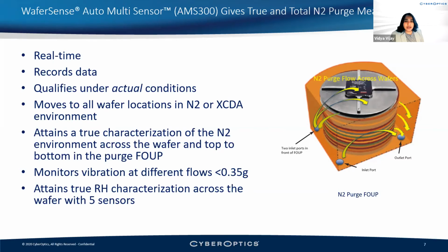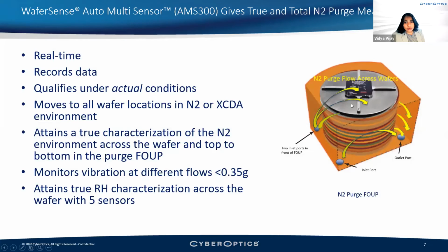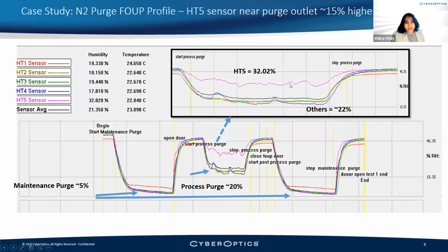So as it goes, it records data and communicates wirelessly via Bluetooth. So the customer can see what is happening when they do a process change or an improvement. For example, here, there are 5 humidity sensors as we saw. There is one in each of the levers here, and the fifth one in the center. The fifth one usually runs hotter than the other sensors because it is closer to electronics. So we had to provide some type of correction curve for that sensor.